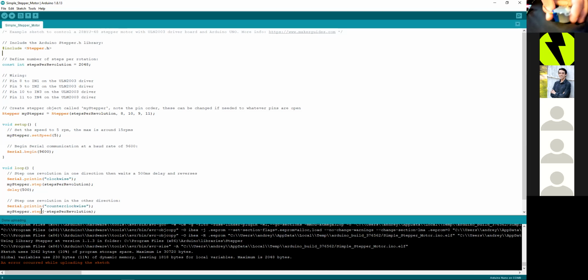That's a stepper motor. What this program does is it rotates one way clockwise. Then once it's fully done, that is 2048 steps or one rotation, it flips back counterclockwise. And it's just back and forth and back and forth.